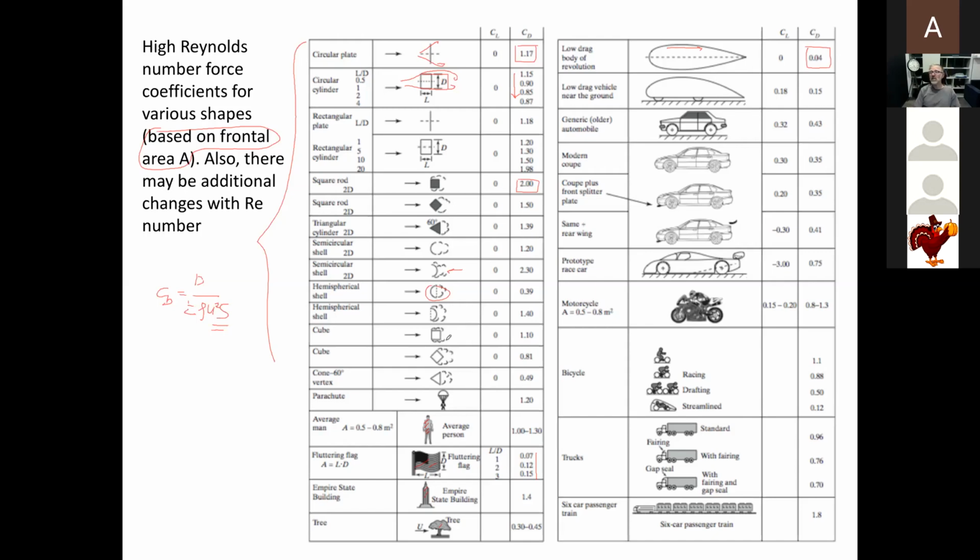And then we can do examples based on this table. In terms of problem solving, in the case of pipe flow, I told you to put the Moody diagram under the pillow and try to remember it, because with that you can solve all the pipe flow problems in the world. And this one is in a way similar, because you can try to estimate the drag of something out there, find something similar and make a judgment which is probably not too far off. That's the big advantage of this type of diagram.